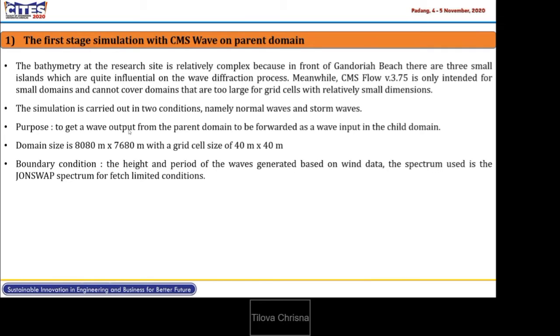So why do we need to simulate in two stages or two domains? Because the bathymetry at the research site is relatively complex. There are three small islands which are quite influential on the wave diffraction process. CMS wave can cover a large area, but CMS flow version 375 is only intended for small domains and cannot cover domains that are too large for small grid cells.